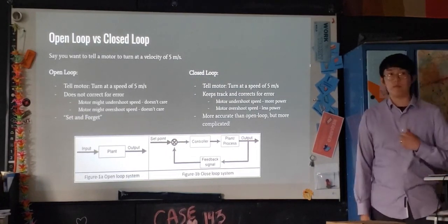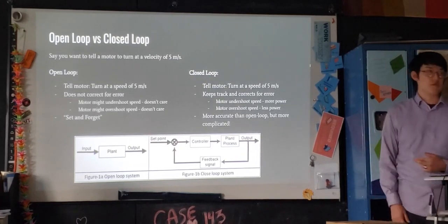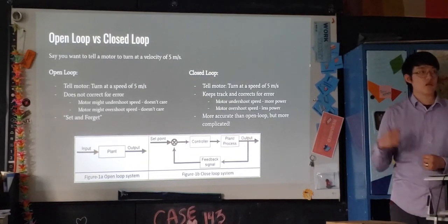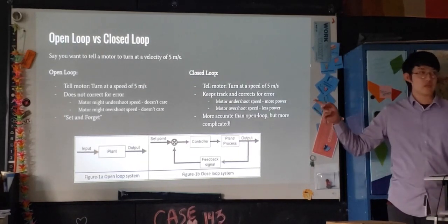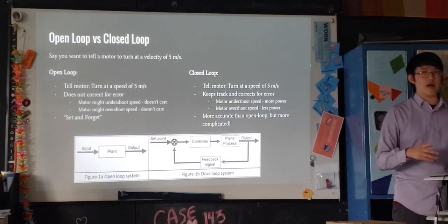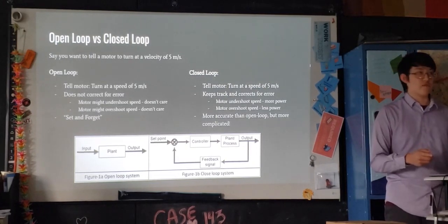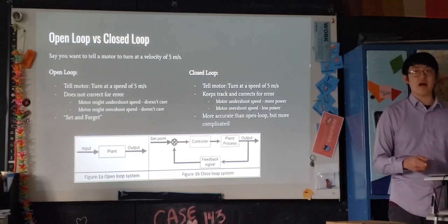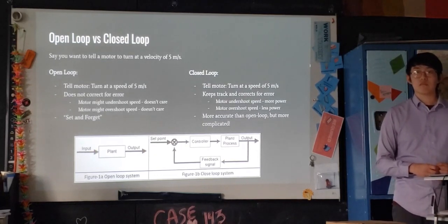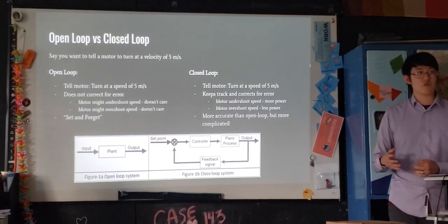Yeah, so on the robot, anytime there's PID control, that's closed loop. Anything that has the PID or feed forward, that's closed loop. Open loop is the equivalent of percent output. On the robot, I don't believe there is. If there is one place, it is the swerve drive. We have used it a little bit for the swerve drive. Yeah. We did just like percent output of the joystick. Right. And then converted that directly to the motor voltage. Right. So for swerve drive driving,